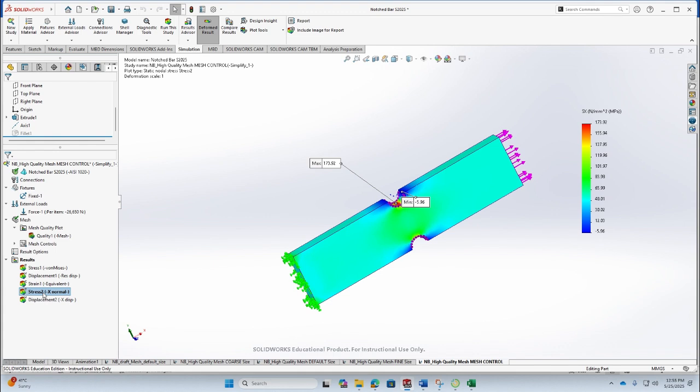It's only about calculating the component of the normal stress. Remember that example that I solved in the class where we had two strain gauges, one along the x-axis and one along the y-axis? Although the force was being applied only along the x-axis, we still had a strain on the y-axis, and from that strain you can also calculate the stress along the y-axis.